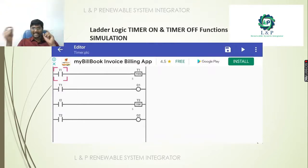Let us see how the T on will work. T on will work when the input is enabled: it will count 1, 2, 3, 4, 5. Once we get the timer done bit, then our output will be on.